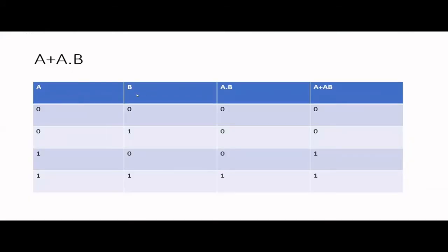I told you there are two inputs, A and B. So 0, 0, 1, 1, 0, 1, 0, 1. This is the pattern you have to put the inputs, right? And A and B, right? So it's not the multiplication, but here you should know that both inputs should be 1, then only your output will become 1. So I told you, you can do a trick like a mathematical multiplication, but it's not the case. But as a shortcut, you can do it like 0, 0, 0, like 0, 1, 0, like that. Okay. So all the inputs should be 1 to get this as 1.